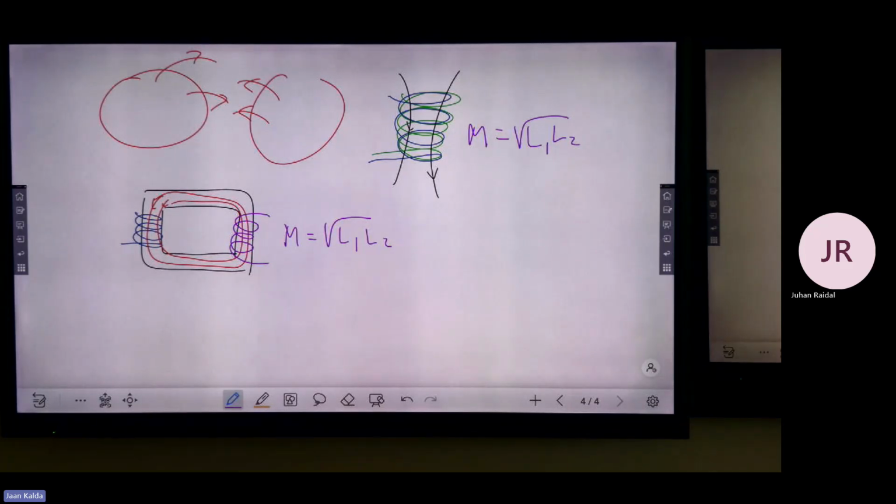If you want to have a completely, totally linear response, meaning that you let sinusoidal current into one loop and you want a linear sinusoidal voltage to appear on the other: if you take that ferromagnetic core, it is not strictly sinusoidal because the core is non-linear.